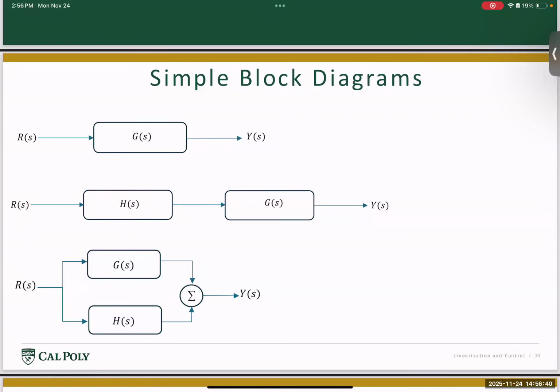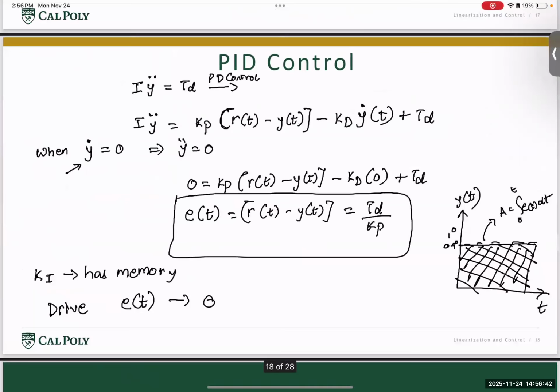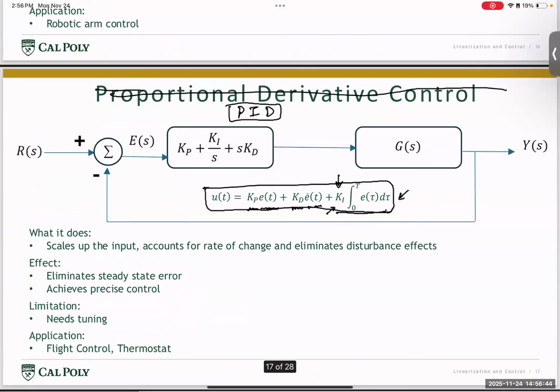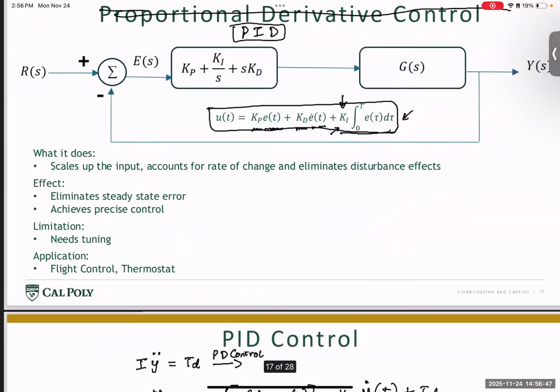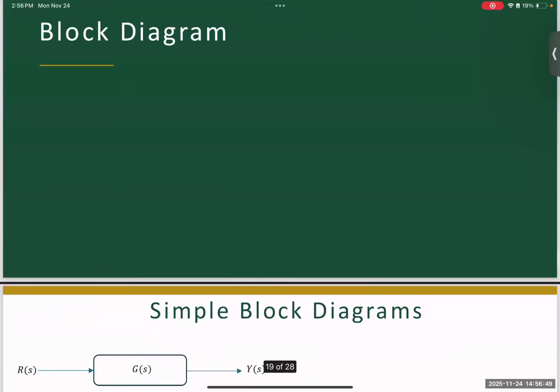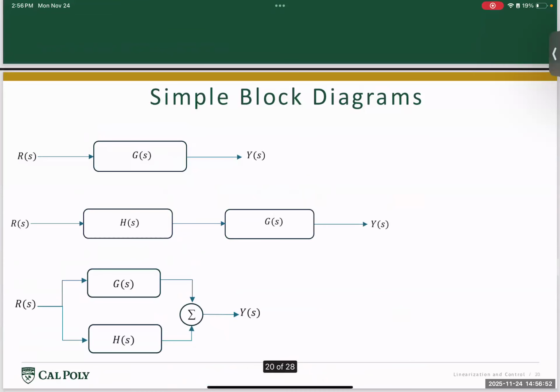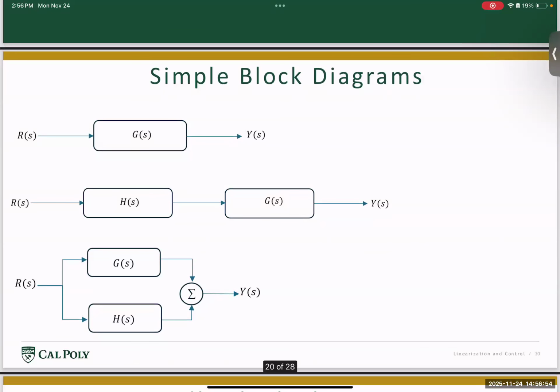But still, these equations tend to be complex, where we looked at some of these examples as we add different amounts of control inputs. So one way people have identified to simplify this whole process, understand the dynamics of the system, and also come up with efficient ways of designing control is to represent each component of the system as a block. Here, basically, each block represents a differential equation, or it could represent an algebraic equation that talks about what the dynamics of the system are based on different inputs.